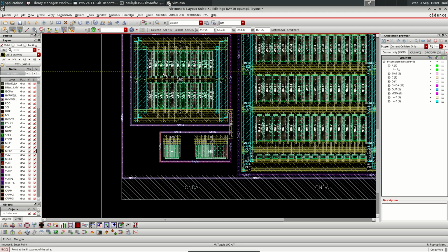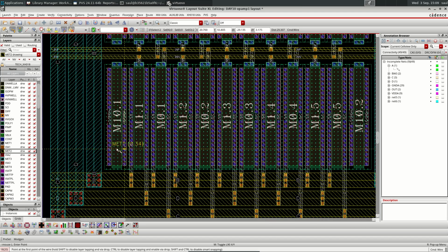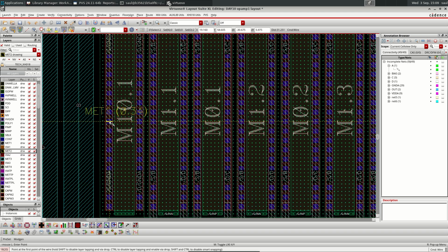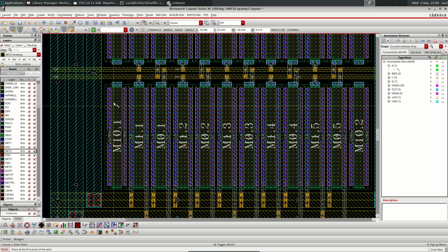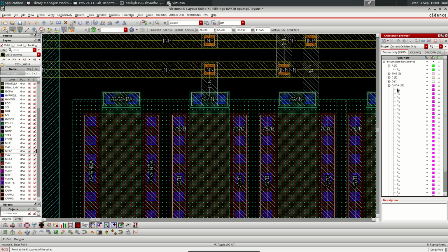We have node D and node C, but now I remember that I have things that are disconnected inside the modgen. For instance, this dummy. The dummy should be connected to ground, the gate, drain, and source, and they are not connected right now. So let's take a look.